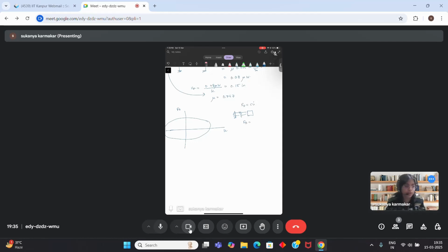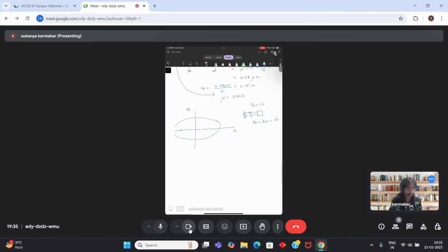It will be because of the spring as well as the damper, but because of the spring, there is no energy dissipation, because the stiffness is constant, right? It is linear elastic. So your loop is just rotating.